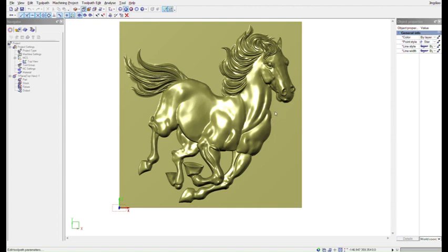And then tool shape, you have to select the exact tool shape, otherwise it will distort the model. So I'm going to delete this tool and add what I am going to apply here. I have made some tools, that is the taper ball end mill. In taper ball end mills, in this shape there is a curvy edge and the taper appears.